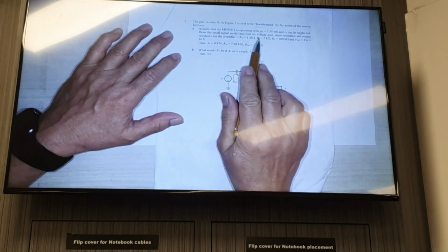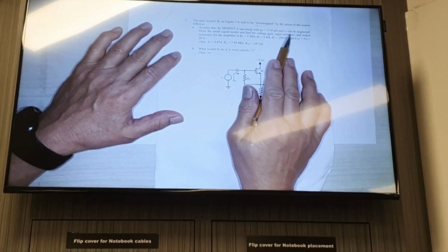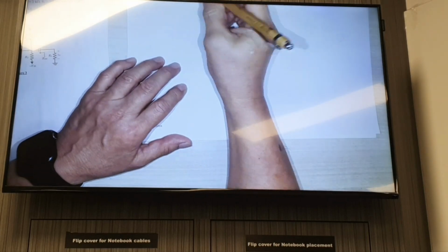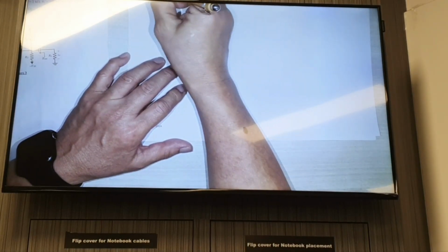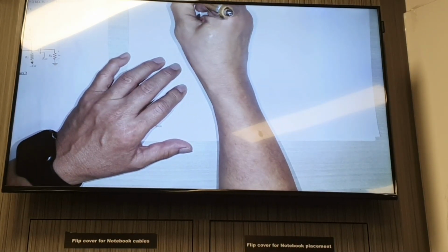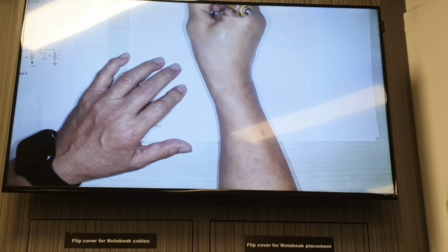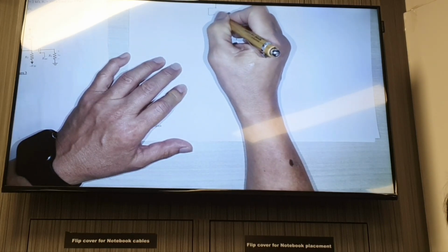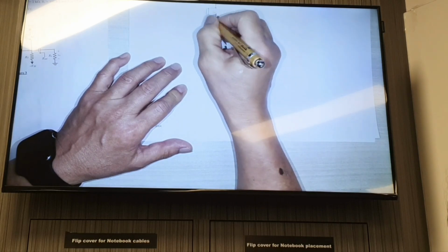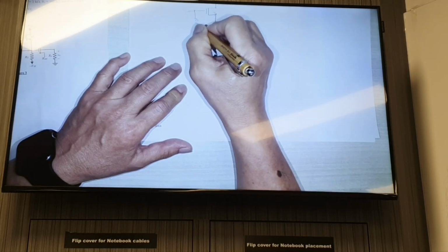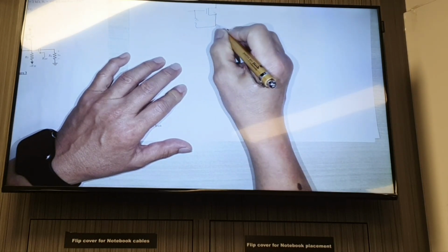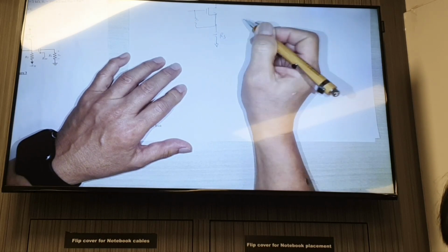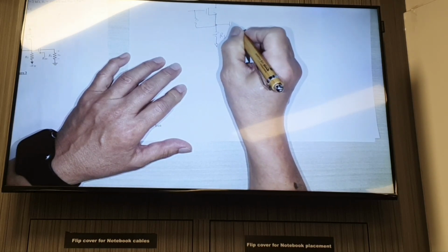Okay, so here we are given gm and we are neglecting ro. So we can draw this as this. This is your question 3 of tutorial 8. We have this transistor here, and we have this resistor that is bootstrapping the source, and there's a source connected to the load.